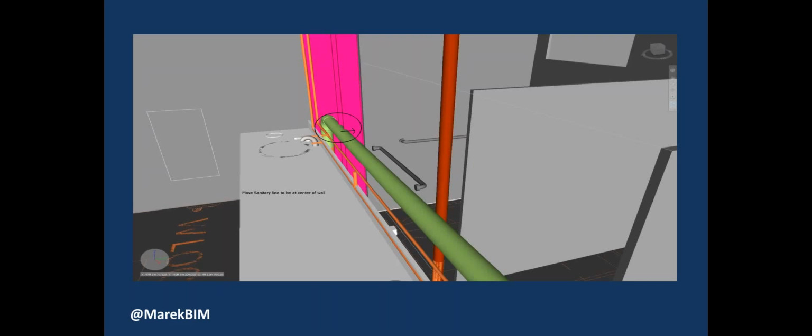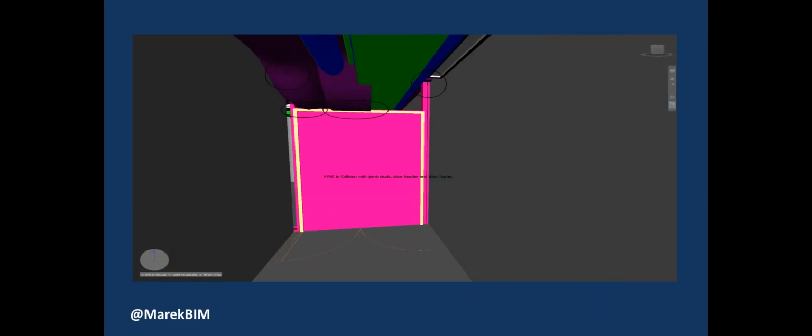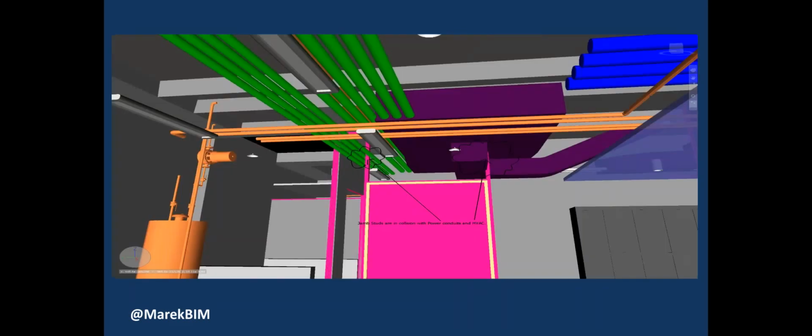And the thing about metal framing is critical framing has to stay there. It can't move. But a lot of the other framing can be fluid. If you're hitting a corner or something like that, that can't be moved. But if you're hitting a stud in the middle of that wall, generally we can move over and accommodate the MEP items. This is duct colliding with headers and jam studs. Once again, we're hitting jam studs.